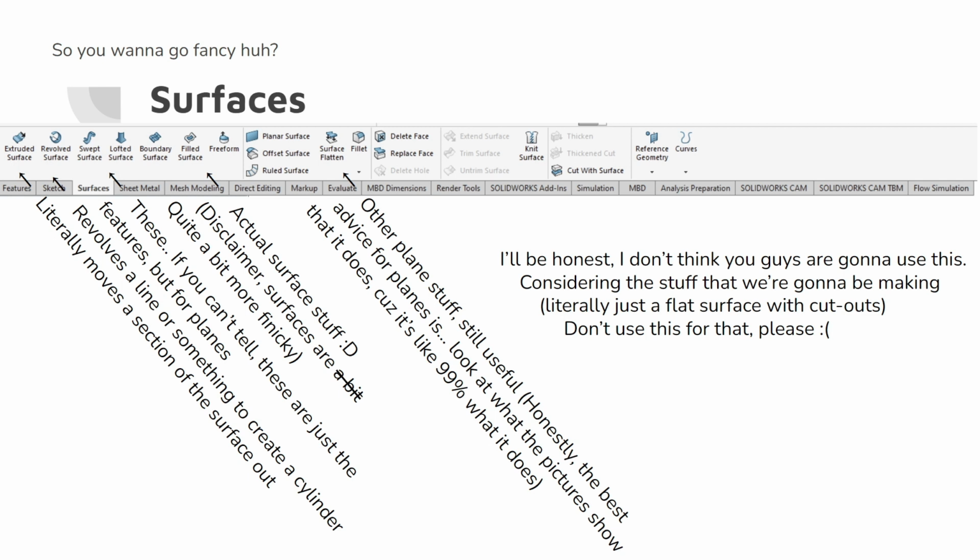Now, if you make the surface into a paper box, that is considered a body. But SolidWorks doesn't treat the whole thing as a body automatically. You gotta do knit surface and some other stuff. I found that out the hard way.